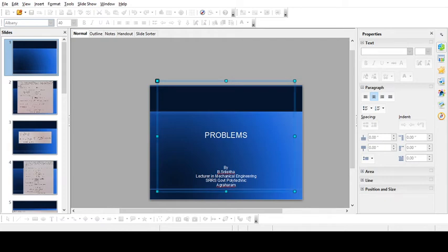So it is given that a cylindrical bar. Cylindrical bar means it will have a length and a diameter. So the diameter is 20 mm and the length is 1 meter. It is nothing but 1000 mm. Now during this tensile test, the longitudinal strain is 4 times the lateral strain. Means lateral strain by longitudinal strain is equal to 1 by 4. That is nothing but 0.25. It means our Poisson's ratio is 0.25.